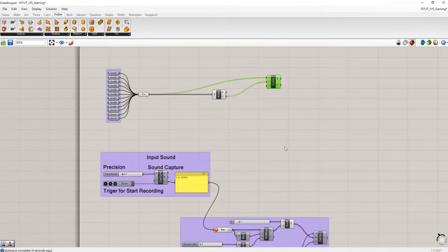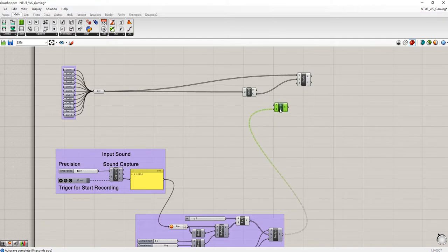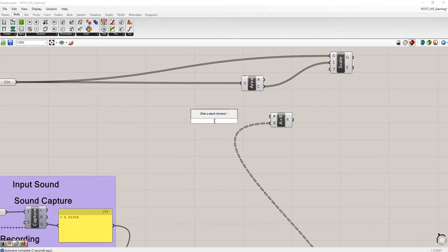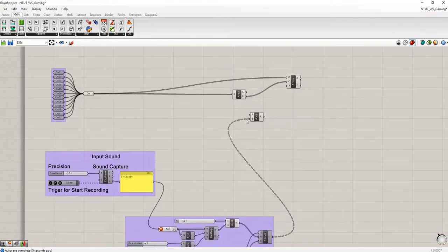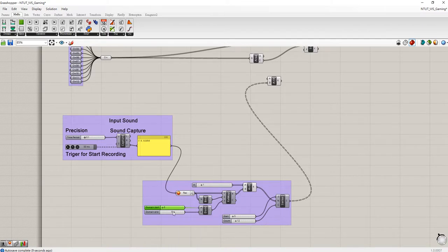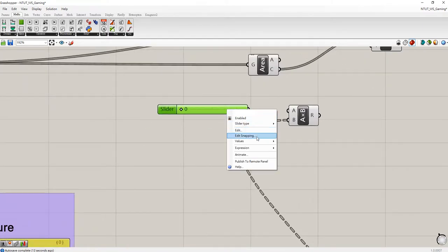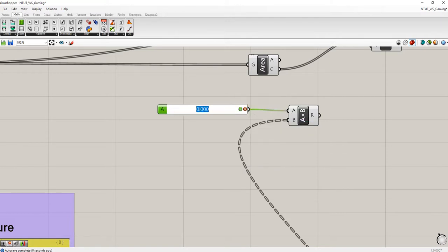And for the vector, we do two adjustments. First thing, again, we're using multiplication right here. Connect this one to this side. And I think the number we use is a floating number, 0.02. So let's copy this one to here, and we can change the number. Change this input type to floating point. Connect here, and this is 0.02.